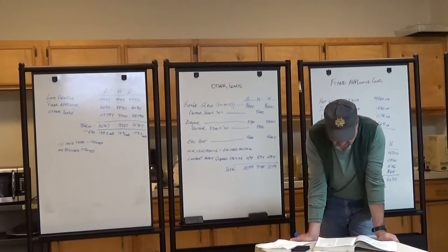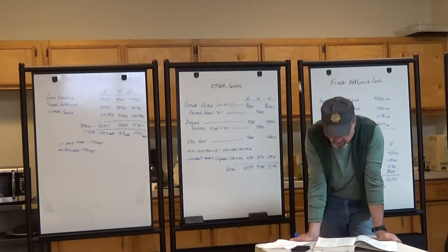But if you look at that first part of 250.66, there's a table that it references. It says the size of the grounding electrode conductor at the service at each building or structure where supplied by a feeder or branch circuit, or at a separately derived system of a grounded or ungrounded AC system, shall not be less than given in Table 250.66, except as permitted in (A) through (C).